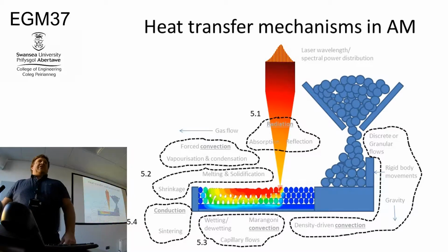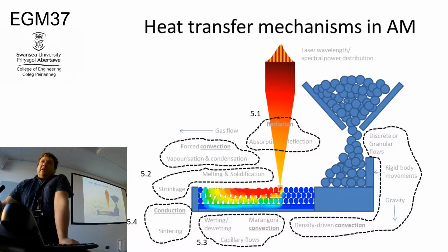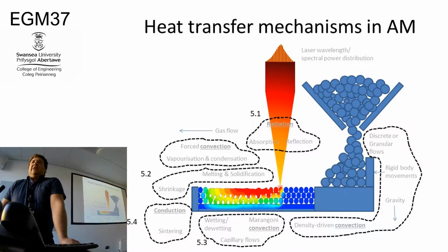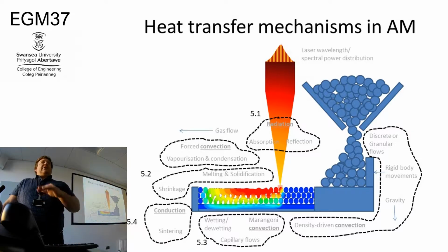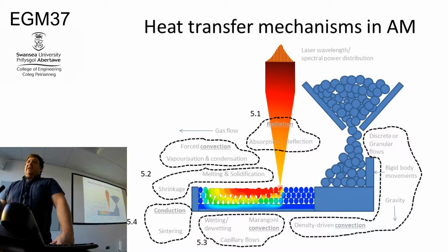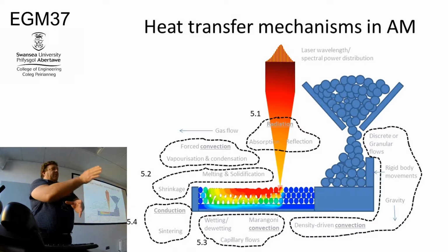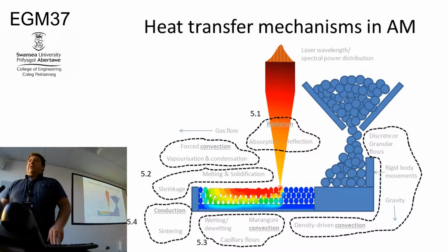We've also got a discrete nature of the powder side of the flow, so when you're pouring particles down a hopper and they settle on a base plate and into the powder bed, they may segregate. So there's a density-driven segregation of the actual discrete particles as they come into the bed. Because of that densification, you get a stratification of the powder, that itself can lead to differences in properties and melting during the different stages. You've also got the wiper, which plays its own role in wiping the powder across the bed, and also leads to the segregation of the powder. So a lot of different aspects.